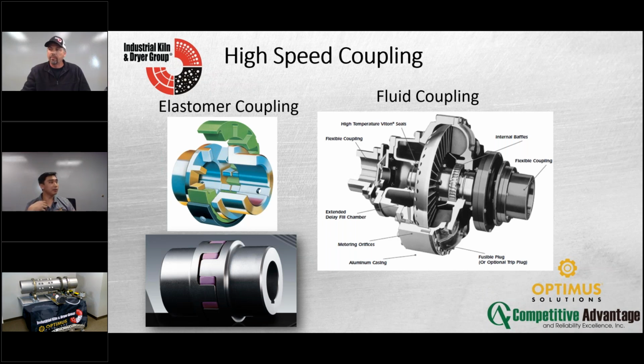I tend to like the fluid couplings a little bit more, in the sense that when you turn the unit on, the fluid has to engage. Correct. When the fluid engages, it gives it a little bit of lag, to where as it turns, you don't just immediately go. It's a softer start. It's a soft start, yeah. It's like the soft starts on your router at home versus it goes immediately up. Correct. Because when it goes from 0 to 100, that does add a lot of torque in there, and if you don't have it aligned right, it's a lot less forgiving. Whereas in the fluid coupling system, it's a little bit more forgiving.